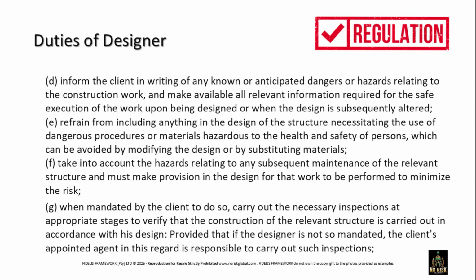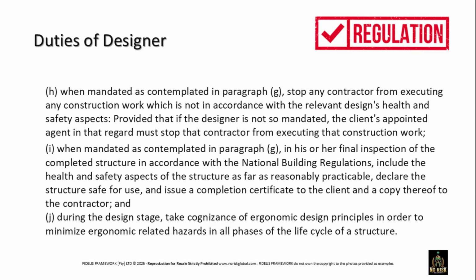Designers must inform clients of any hazards related to construction work and conduct necessary inspections. They should consider hazards related to maintenance and design changes. Designers must stop contractors from executing unsafe work and ensure compliance with building regulations. They should consider ergonomic design principles during the design stage.